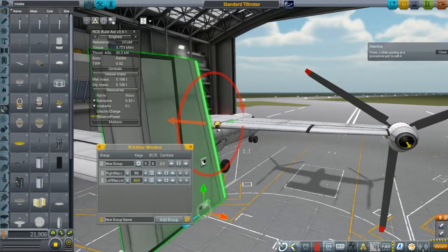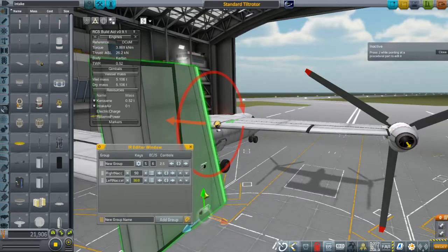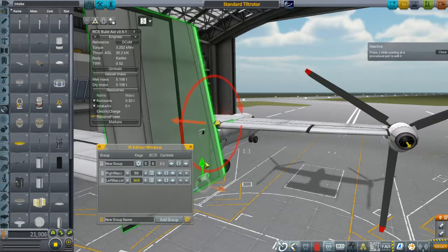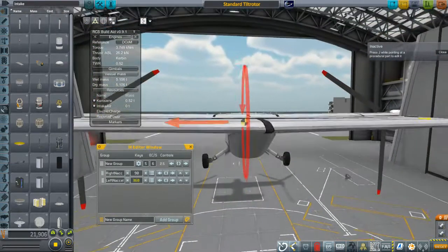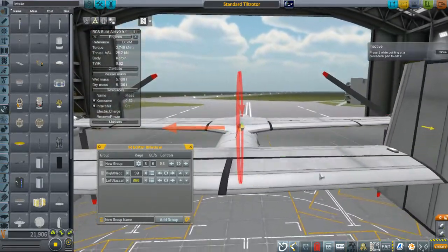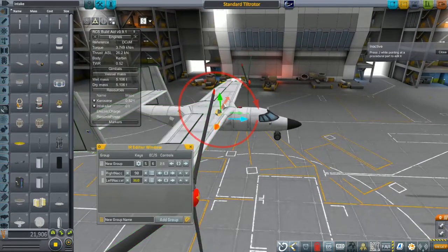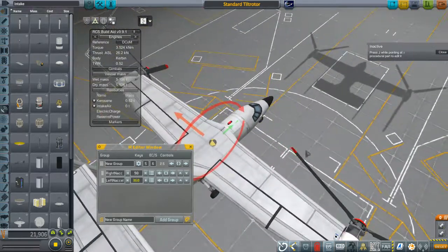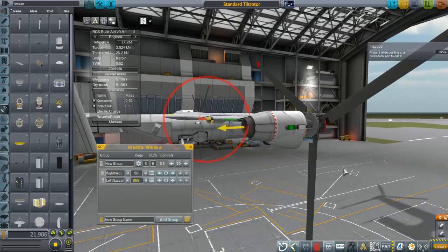Another thing we can probably do is shift this whole assembly up. That's not producing enough of a mass difference to matter, so we actually have to get into adjusting tiny portions. Mainly this is important because when you're in all forward mode, that massive torque ring says the engines are going to pull this thing forward over the top of the center mass and try and push the nose down as it flies.